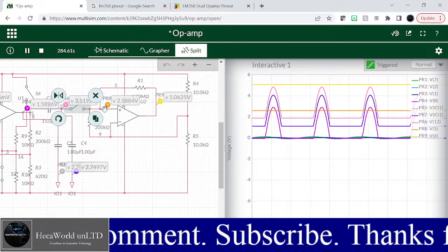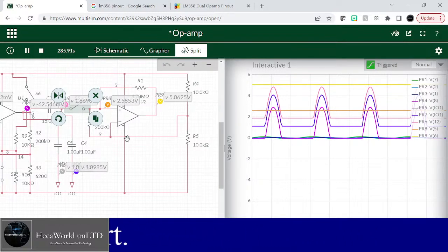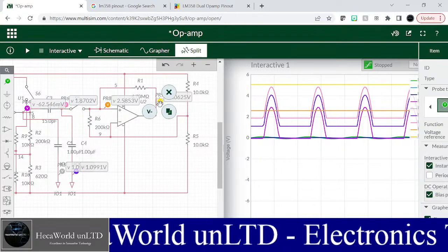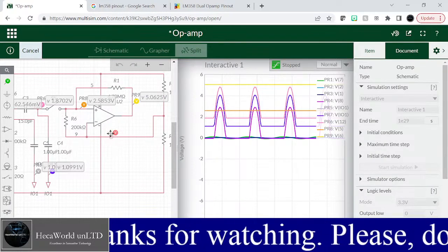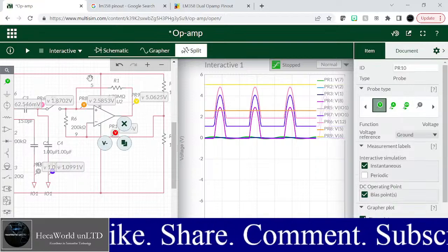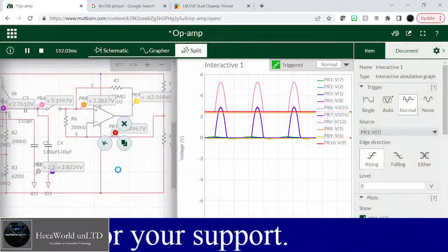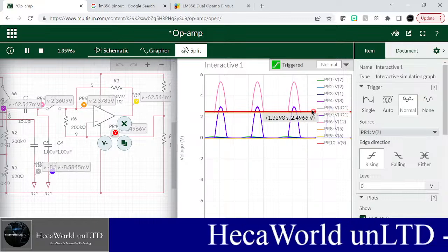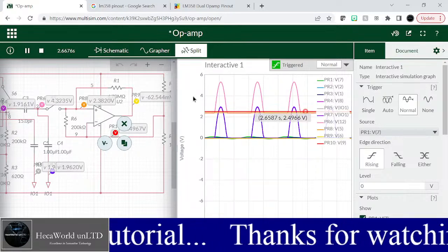And it's telling me that what I have in the, so maybe I should put another probe here. Let's put a 10th probe and see. I'm going to stop this simulation and put a 10th probe. So copy, and I'm going to put it here. So let's see what voltage the 10th probe will give us. All right. The 10th probe is about 2.49 volts.